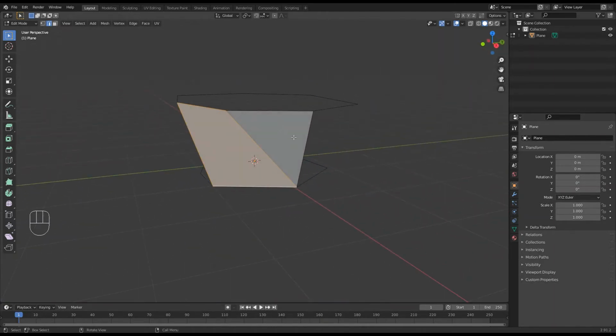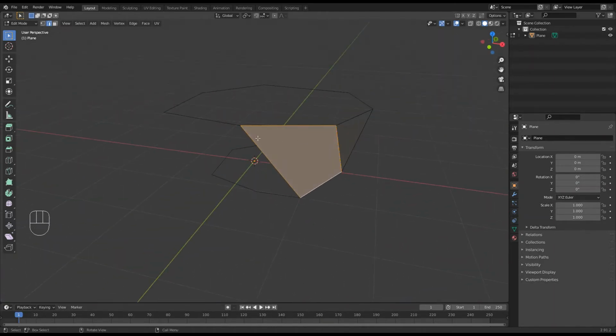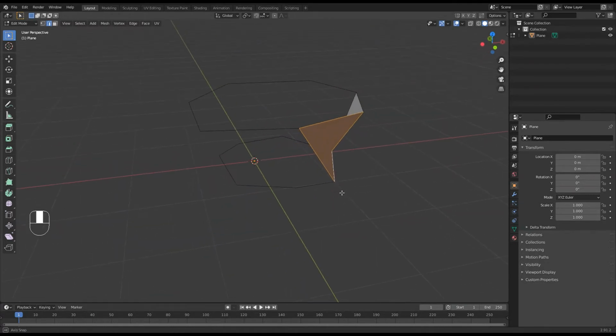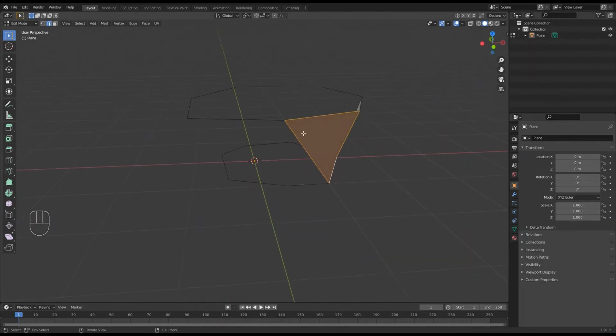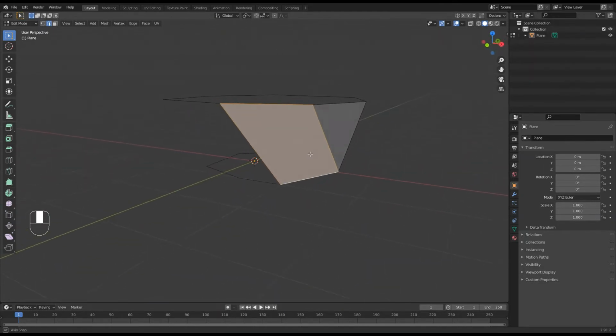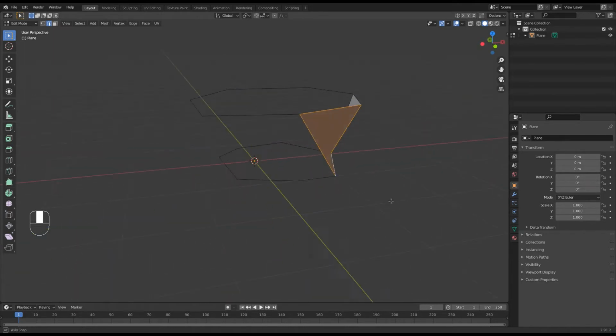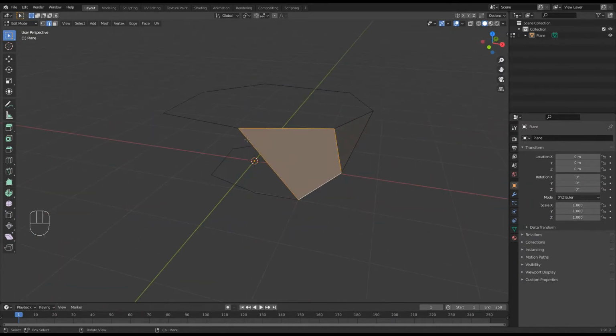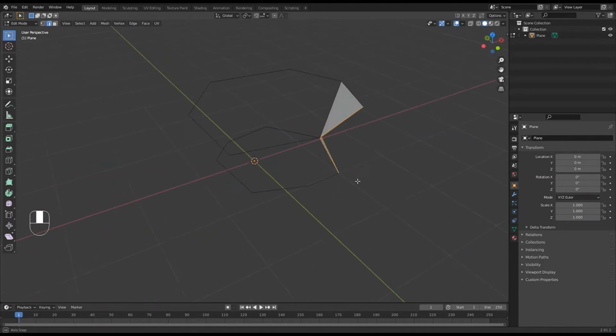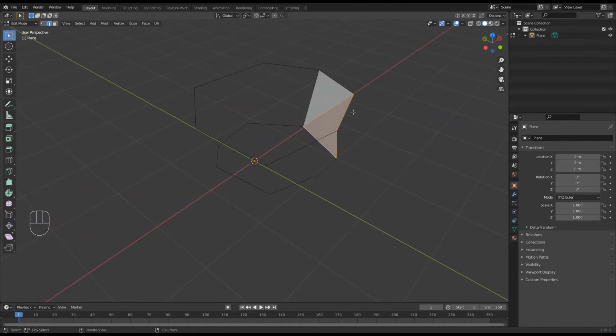So we've actually got a triangle there, but here you've got a 4-sided surface. And you can see how it's taken on a really weird curve across here. So that's actually not a good idea. One should be filling this with triangles. You can mix 4-sided surfaces and 3-sided surfaces, but you need to make sure there is a diagonal line across here to take this change in surface.